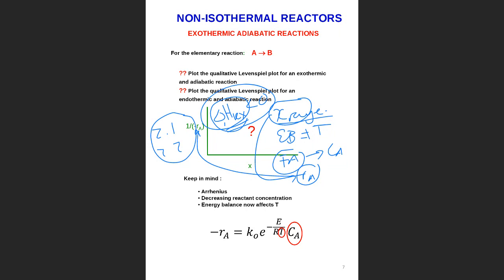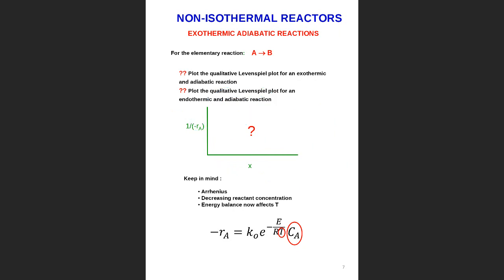This is the one thing that I want to teach you: not just to accept the answers you get. What happens then is you get a pressure drop of 500 kilopascals per kilogram of catalyst and you don't think about whether that's realistic. That's half a megapascal pressure drop, right? And I realize at this stage you are just so glad that you get an answer that you don't care about what the answer is.